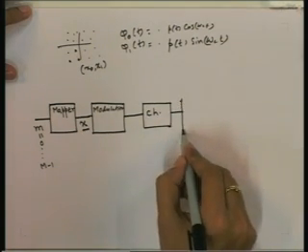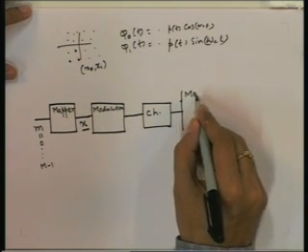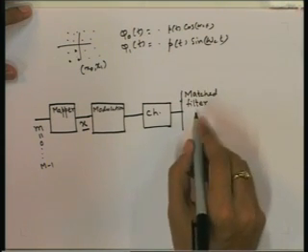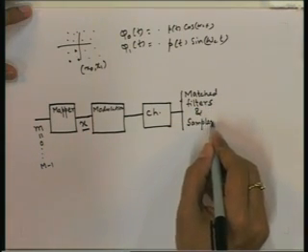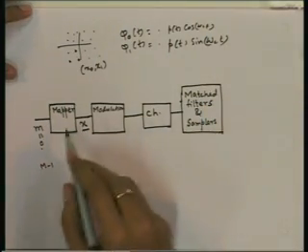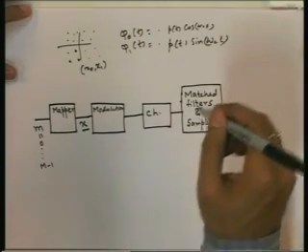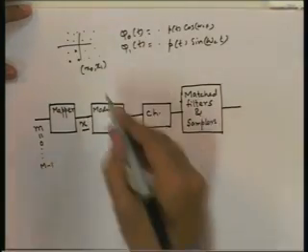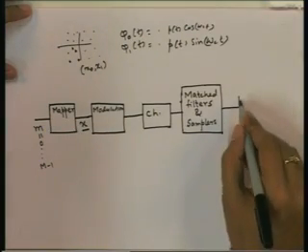Then we do demodulation, which is basically matched filter banks, so matched filters and samplers. So, what we are drawing is basically a matched filter receiver. This will give as output the received vector, the estimate of the vector which was transmitted, some point say here, and then we have the detection.